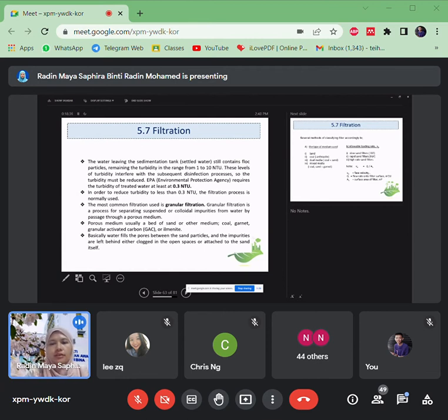Usually we use sand or other media like coal, garnet, GAC or ilmenite. Our aim is to treat the water to a minimum of 0.3 and below, so it is very clarified.